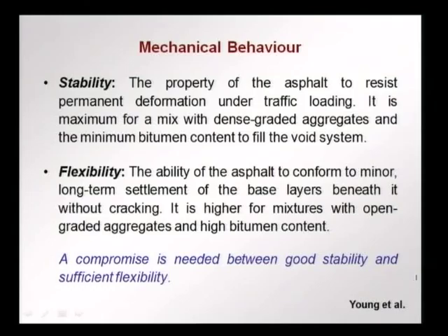Stability is the property of the asphalt concrete to resist permanent deformations under traffic loading. That means, it should not undergo significant plastic deformation as time goes on under traffic. It should remain plain, it should remain integral and not become bumpy or undulating with time.